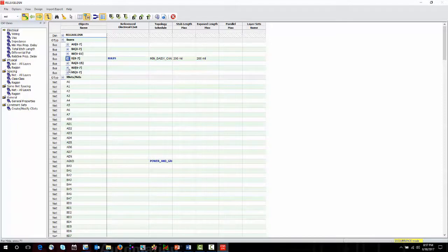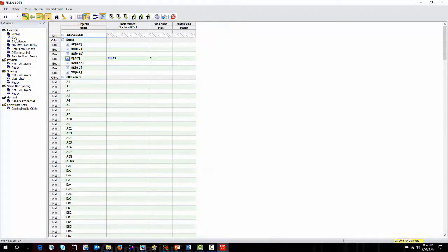The last thing that we're going to do for the constraints on this net is go to the vias rule sheet. Actually, let's expand this back out again. And we're going to turn on the matched vias. So no matter how many vias the nets end up getting, 1 or 2, they have to be the same number on each bit of the bus.